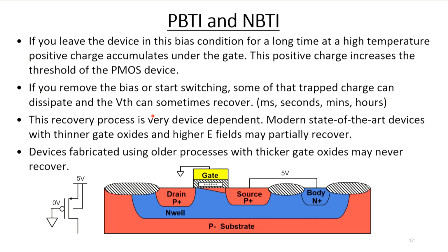Now, the time it takes to recover can vary. Might be milliseconds, might be seconds, could be hours. That's part of the insidious nature of this PBTI and NBTI stuff. So this recovery process is also very device dependent. Modern state-of-the-art devices with thinner gate oxides and high electric fields, they may partially recover, but devices fabricated using older processes with thick gate oxides, there's no guarantee that they're ever going to recover from the threshold shifts that you experience with NBTI and PBTI.